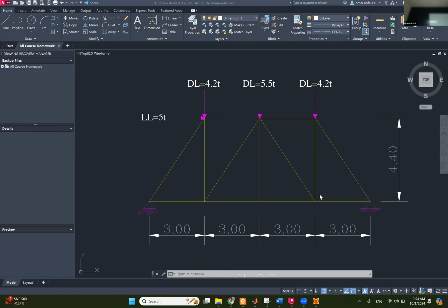We always give you the beam with a distributed load. Okay. So if you draw this truss on a software and you put a bunch of loads, and I didn't tell you in the header of the problem to include the own weight, you can't include the own weight of this truss, because usually when we do analysis for trusses, we neglect the own weight with respect to the external loads that are on